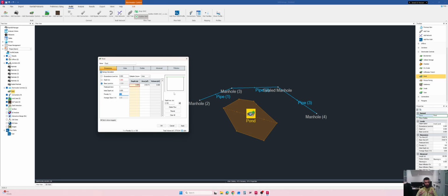But this is for the basics. How you can use it is, this will be a 3D pond, and then you can have the hydraulic analysis within the InfoDrainage. It's not like you have a 2D pond and you will be calculating the tail water manually, checking in the Excel sheets.